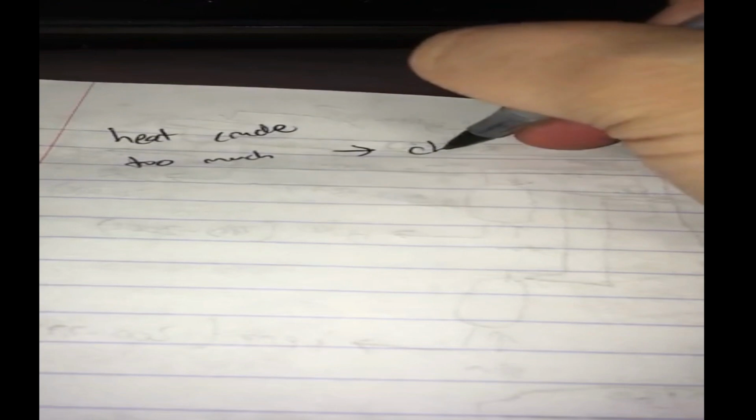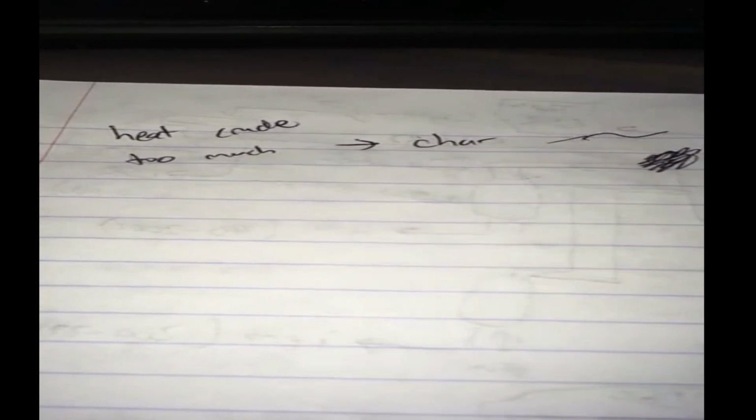So how hot do we heat the crude? Well, we notice that if we heat the crude too much, or oils in general too much, they start to char. They form carbon residue, right? If you see in deep fryers or something of that sort, or even hotter, you see lots of carbon residue. This is known as coke,